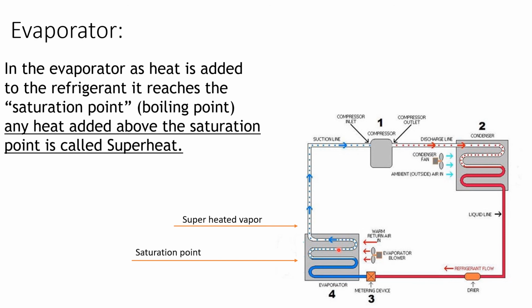Superheat is a really important thing to understand. Superheat is how our compressors are protected in the system. Let me explain this a little bit further. I have this gas or this vapor or this refrigerant going out, and this line set might be kind of cold, but it's still a gaseous state. And it's a superheated vapor, so we've added extra heat to this, and it keeps coming up through the suction line and it enters into the compressor.